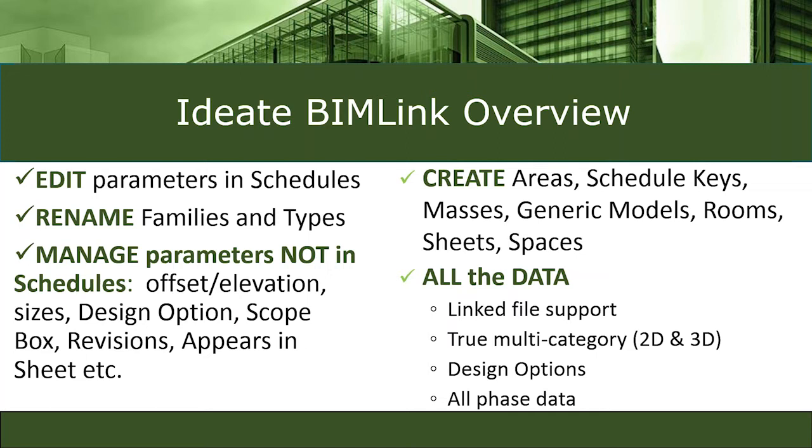And then I'm also going to show you some examples of creating things. We can create areas, schedule keys, masses, generic models, placeholder rooms, sheets, and spaces. And it's very easy to do that within the Excel schedule. So as an example, you might want to create your entire sheet list and then import that into Revit and then be able to place your sheets and title blocks based on that format that someone else has filled out in Excel. And then we're giving you access to, as I mentioned before, all of the data.